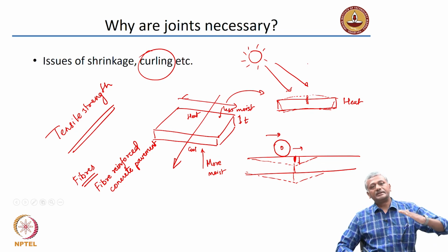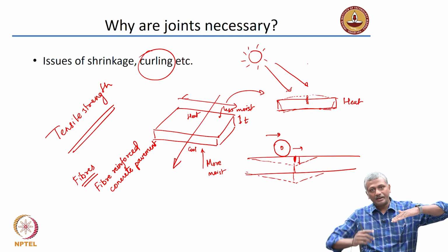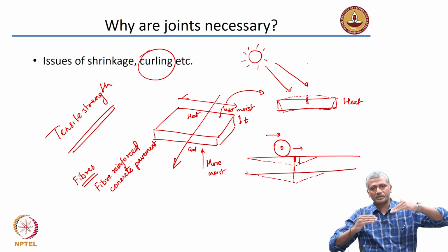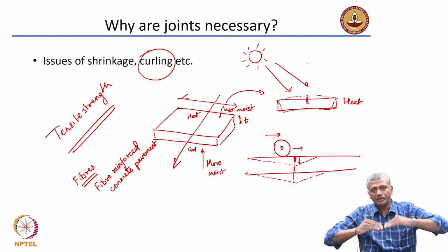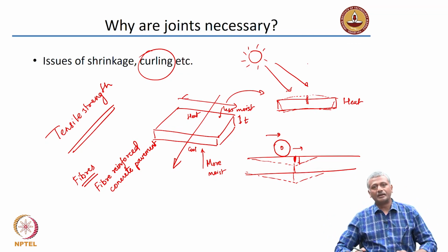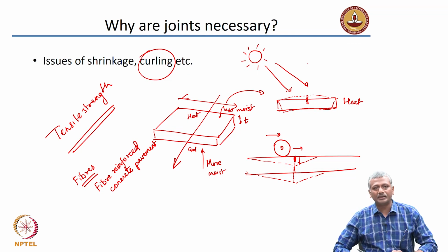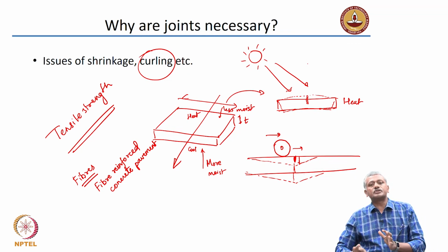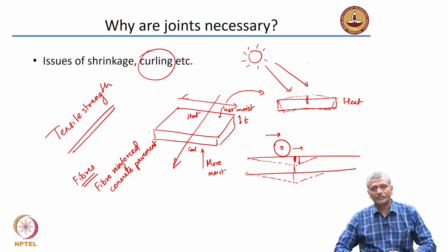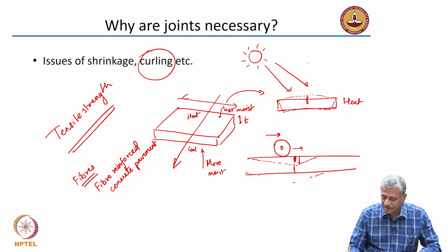At the joint, there will be a major deflection of this slab and the next slab. So, what will happen is, every time that your wheel passes over the joint in the pavement, there will be a big depression in the pavement. That means the wheel will bump there, and that is not very good for rideability. That means your stress transfer is not happening effectively from one slab to another. So, how do we ensure that the stress transfer happens properly? We put in dowels.